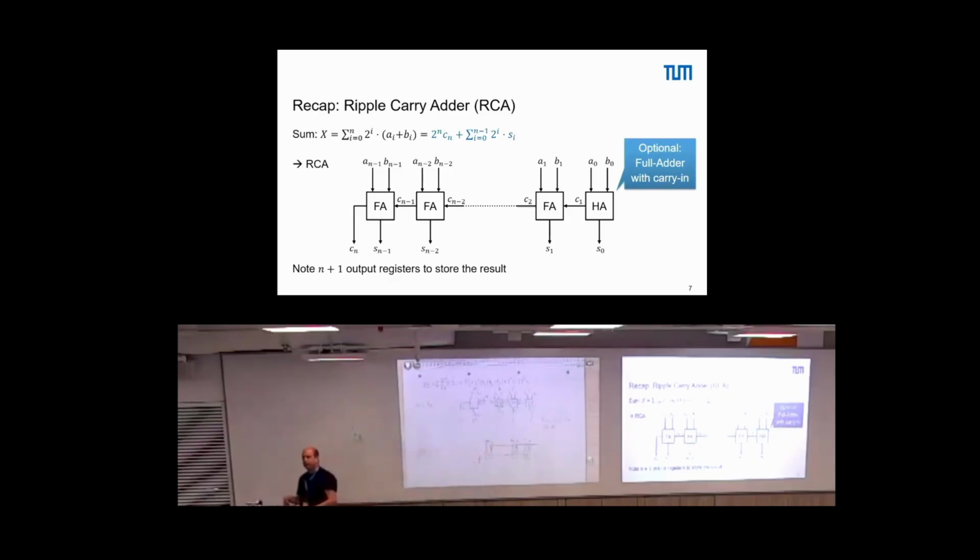What happens if we now enable this subtract signal? If we put this here to 1, in this term here we can add a 1, right? So we are now able to add here another 1. We have already inverted the signal, and we add here a 1, which of course propagates, so the computation is done automatically.